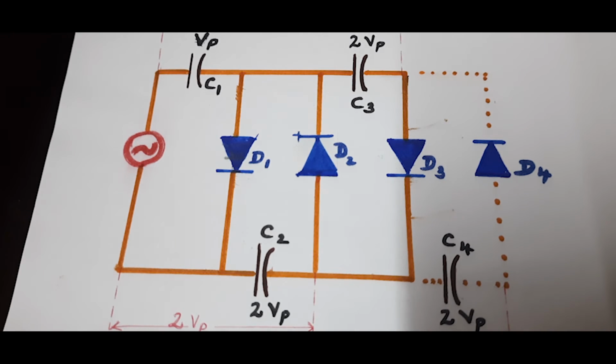So now we have done the experiment for one input voltage. Now it is possible to change the input voltage and repeat the experiment for various values of input. But one important point to be noted to avoid error is that when you change the input voltage, please see to it that you switch off the input supply and then short the capacitors before you change your input.